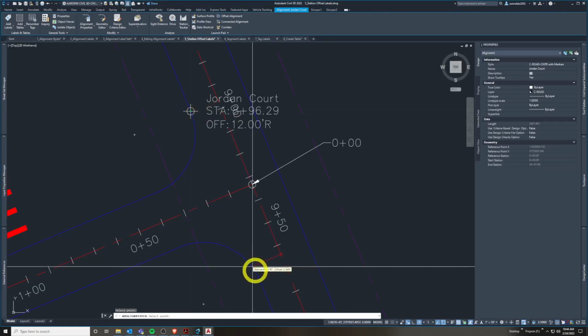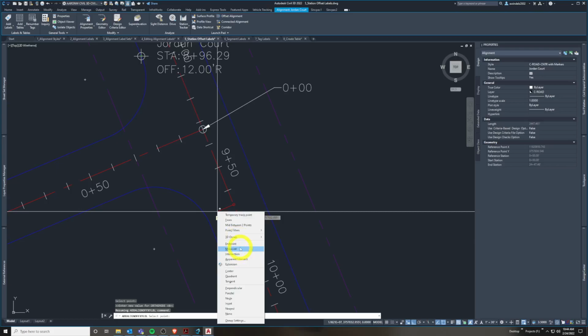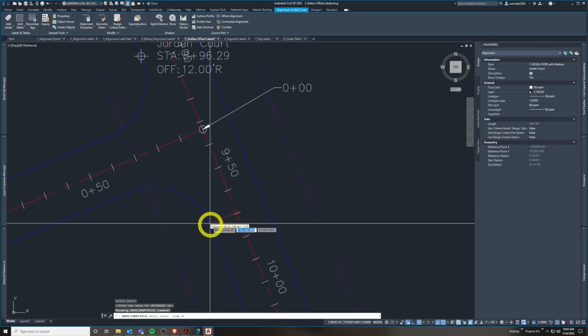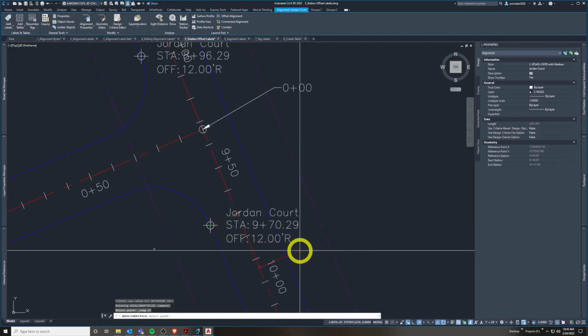I'll put one here. It's also saying to hold shift and right click in this case to turn on an object snap for one command. This is saying I only want to snap to endpoints just for this one command. And then after the command, it stops doing that. It goes back to your running object snaps. So what that means is that it only does square endpoint snaps. Oops, I've got to make sure I see my snap of my square. There we go. Hit escape.